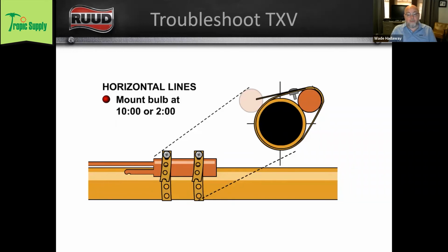And it's really important that you use the mounting hardware that comes with the valve. If you walk up to a system that has an expansion valve on it, and you can grab that valve with your hand and rock it back and forth, it's not tight enough. It's not locked down onto that suction line tight enough to get good transfer, right?